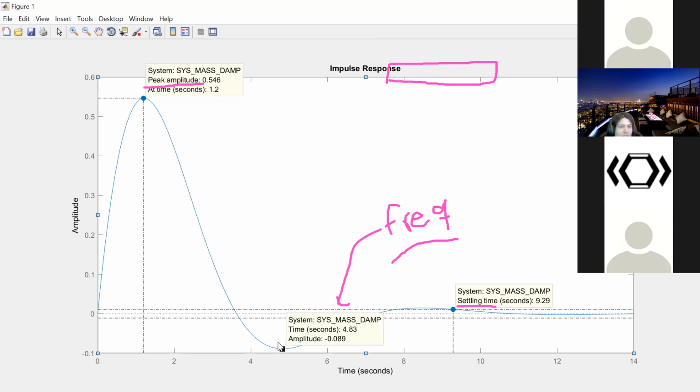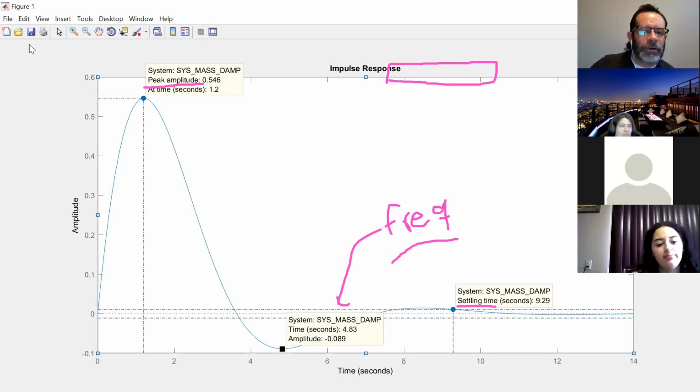Why would the lowest point be of interest? Remembering that we're talking about distance, it's oscillating, going forward and going backwards. The reference is going forward, but we might want to know what is the lowest. In this case, because we're talking about displacement, the lowest value is really when the box goes to the other side with regards to its zero reference. So the positive is when it goes forward, the negative or the lowest would be when it goes backwards, okay? So that might be another thing to consider. Good catch there. Thank you.